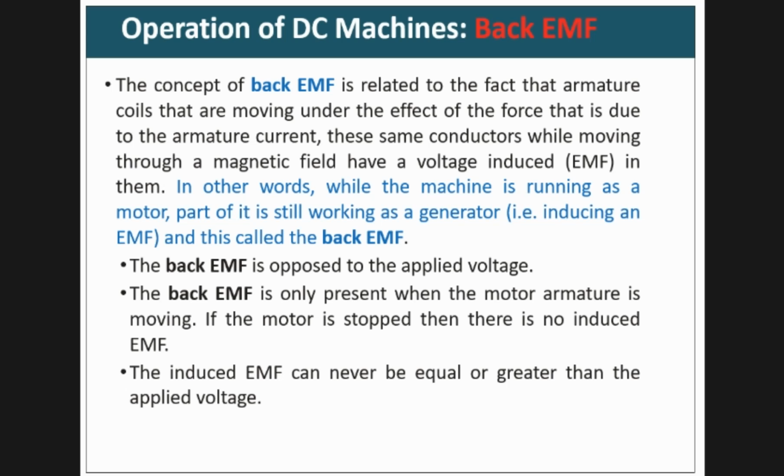And that EMF is in a way that is opposing the rotation, right? So the cause for the rotation is the external EMF that you are supplying to the motor. So the induced EMF will be in the opposite direction to the supplied EMF. So that is what we call the back EMF, right?